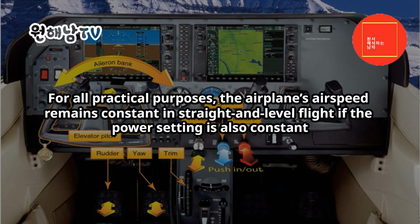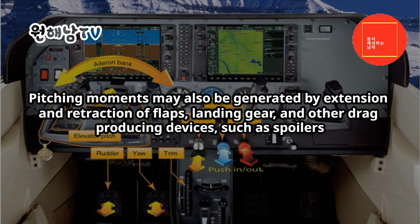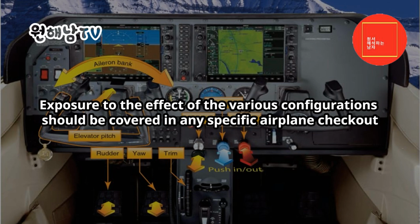For all practical purposes, the airplane's airspeed remains constant in straight and level flight, if the power setting is also constant. Intentional airspeed changes by increasing or decreasing the engine power provide proficiency in maintaining straight and level flight as the airplane's airspeed is changing. Pitching moments may also be generated by extension and retraction of flaps, landing gear, and other drag-producing devices, such as spoilers. Exposure to the effect of the various configurations should be covered in any specific airplane checkout.